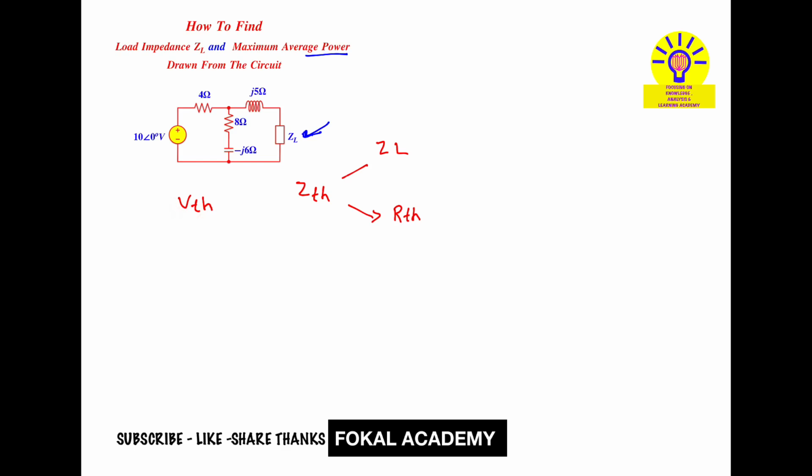How to find VTH for the given circuit? When you are going to find VTH, simply remove this load. After removing this load, the circuit will be redrawn like this. Whatever the voltage is here, that is called VTH. Now observe the circuit carefully. This branch is open, so there is no voltage in this branch. Whatever the voltage across this branch, that is called VTH.